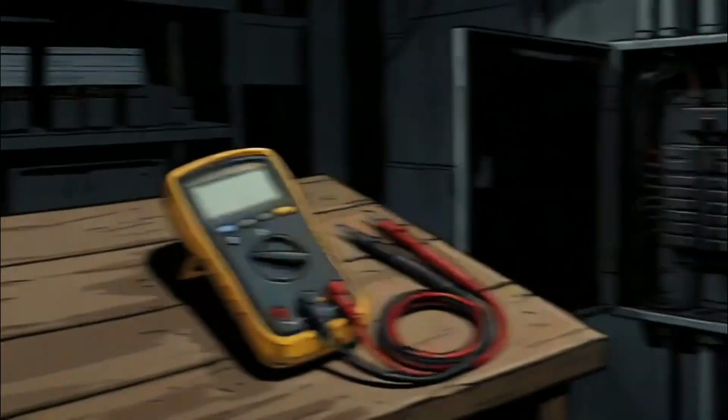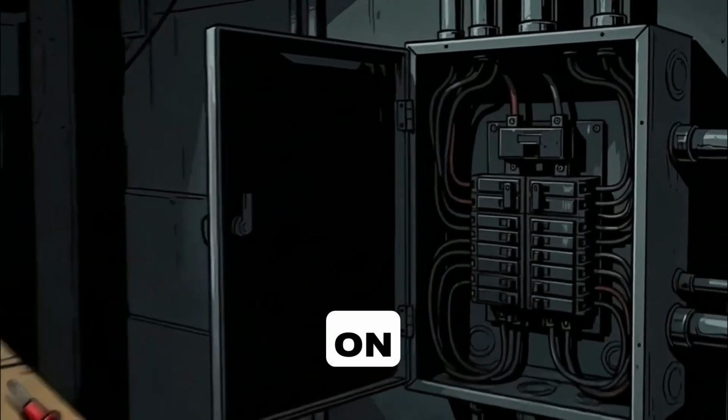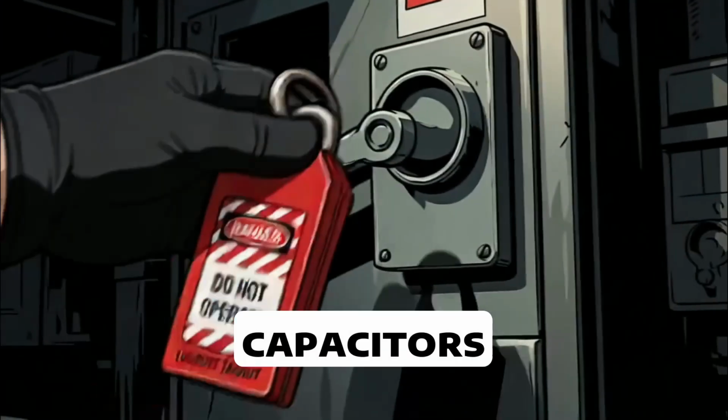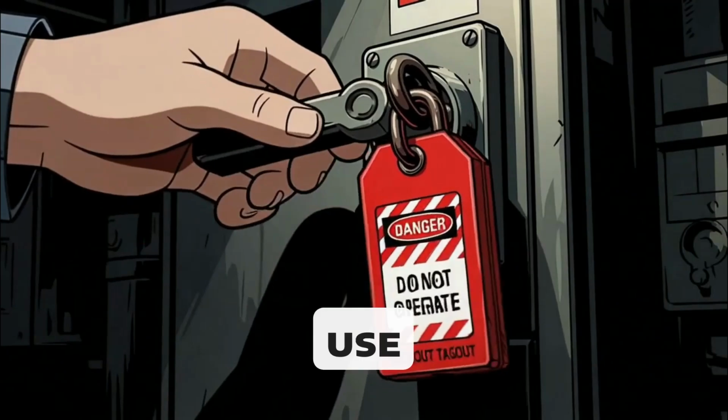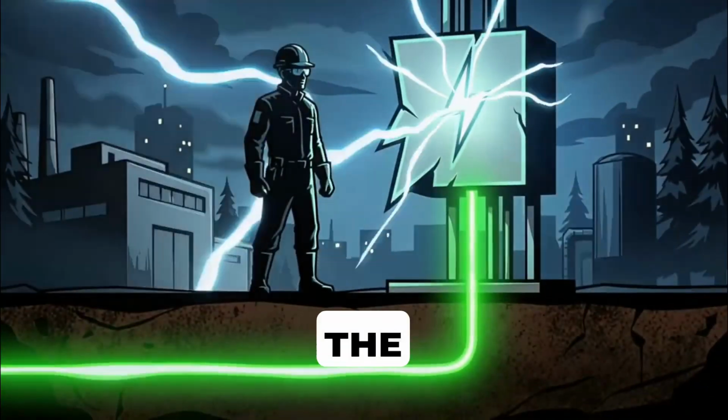Safety rules. De-energize before resistance tests. Never use an ohmmeter on live circuits. Treat capacitors as charged, protect meters, use lockout tagout, respect grounding, and never let your body become the path for current.